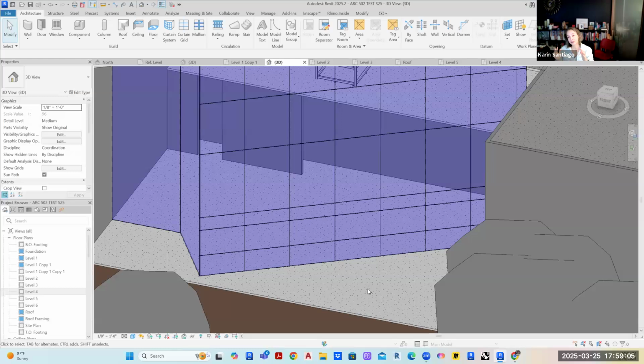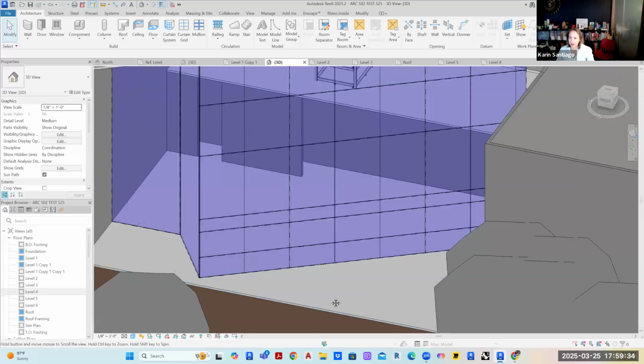That starts to really push it. And then after that, glass gets really expensive. So for that reason, you see these systems tend to have a lot of breaks to make the glass pieces more manageable. These things are super heavy and they're difficult to install. So that's one technical reason, but also they need to be made inside an oven and the oven has to be a certain size. So for all those reasons, glass starts to get limited in size.